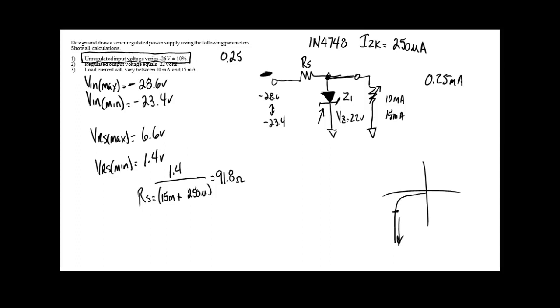Okay. So what do we need to do now? So now we're going to go into our standard resistor chart, and we're going at 5%, and we're going to round this down. So what's our first shot? Yeah, but 91 will never work. So 91, let's check it.